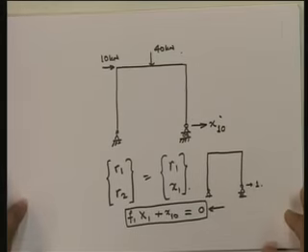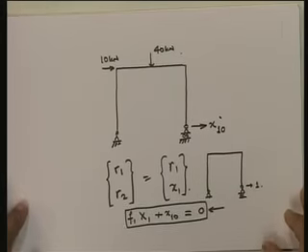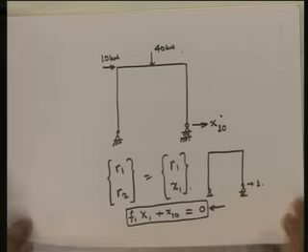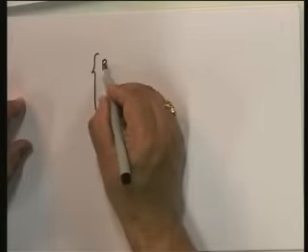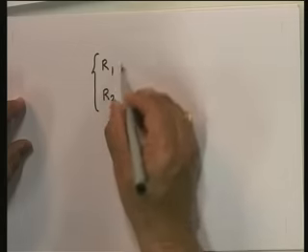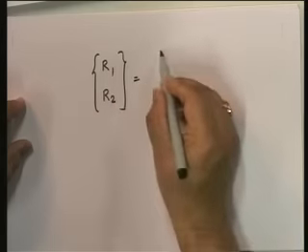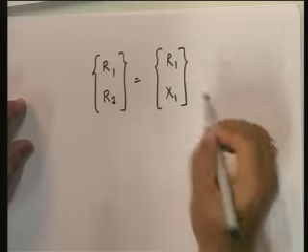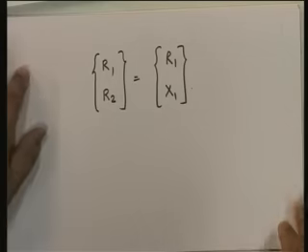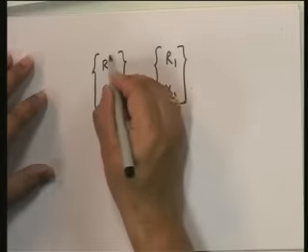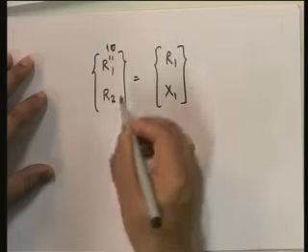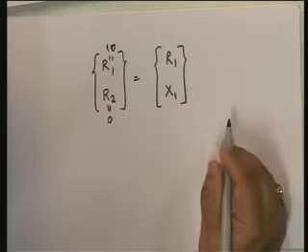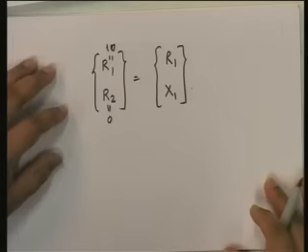In this particular case, understand this, that all that happens is, in the original case, we had R1, R2. In this case, this becomes R1, and R2 is my redundant force. Okay. In the previous case, this was equal to 10 and this was equal to 0. This was what we knew because it was a statically determinate structure.